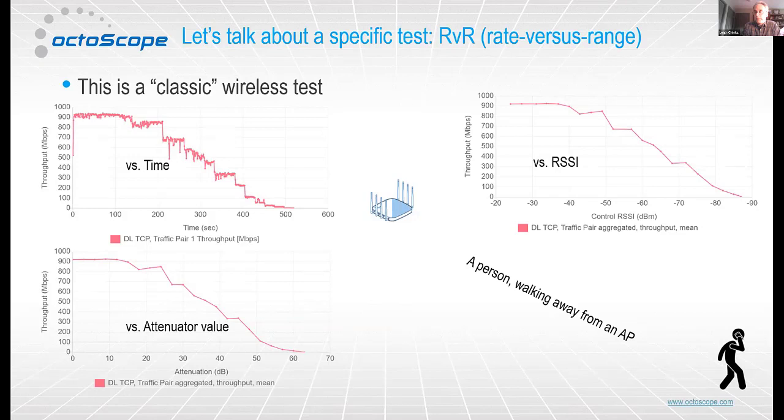If you're using, as you said right at the beginning, nothing around, so roughly a free space model, you would simply convert path loss into distance as long as you know the frequency. And if you have a specific environment, like chairs and tables and things like that, you would simply modify the path loss model based on measurements people have done indoors to describe what a path loss model looks like indoors, and you can convert from path loss to distance based on that model. I can show you some of that. Okay, thank you.